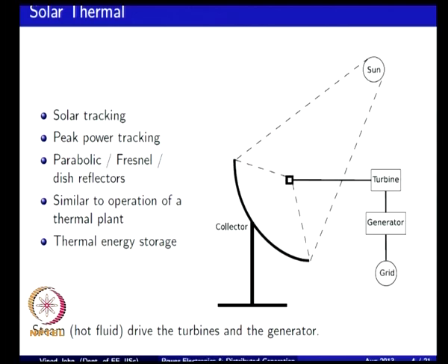Okay. The reason people are looking at solar thermal closely is that the cost of solar thermal is actually lower on a cost of energy basis compared to the photovoltaic, and the efficiency of the conversion is also typically higher. In the photovoltaic system, you are talking about efficiencies of 7 to 15% for common commercial cells, depending on whether it is amorphous or crystalline, etc., whereas you could get efficiencies of the order of 25% in the solar thermal. So, you end up having better cost of energy, so it can be quite cost effective.